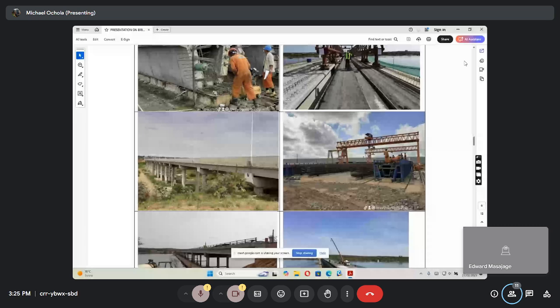So this is now how do you access? Someone will ask, how do you construct a foundation in water? You must construct a platform. Being a water body, we do a jetty. Allow water to flow, and you build a temporary bridge robust enough to take on the weight of equipment that will be plying that route for the construction period. If it's a 3-year period, that bridge must be designed for more than that to be able to withstand the weight of drilling equipment, trucks carrying concrete and the rest of it. So this is a jetty across, supporting construction, then later it is removed.